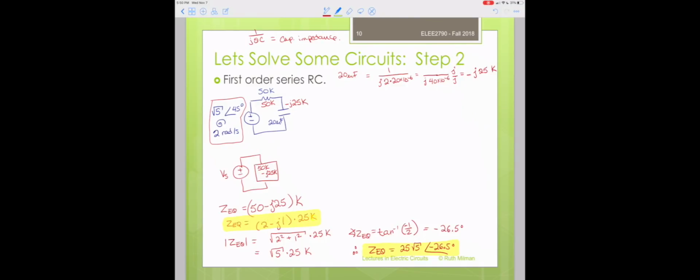So remember that a phasor is just a way of explaining the complex information. We're used to seeing it in the context of an Euler angle with a magnitude, but in fact a phasor is just a complex number. That complex number can be written in any format, even though for the majority of time we're typically most used to seeing that phasor in its polar form.